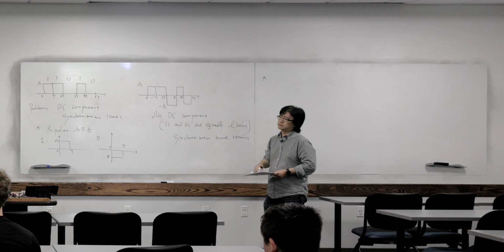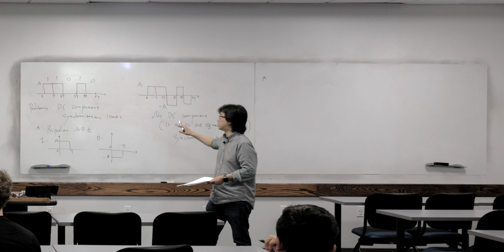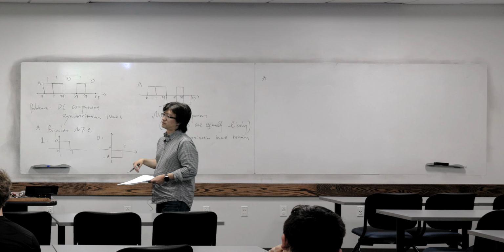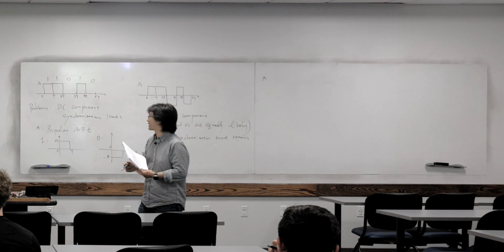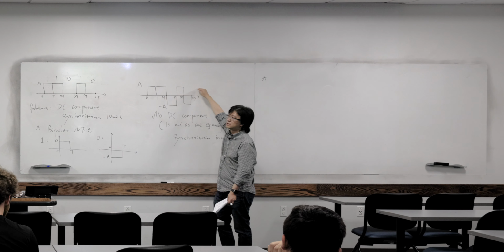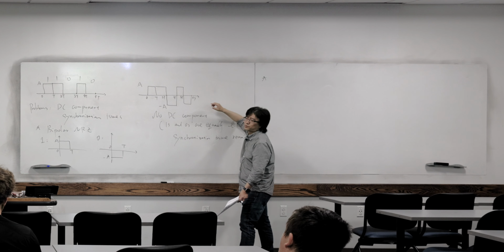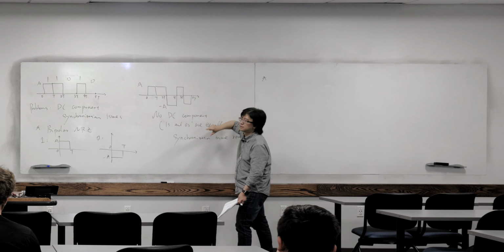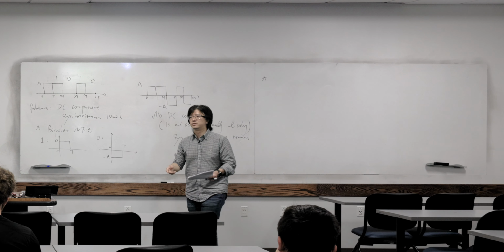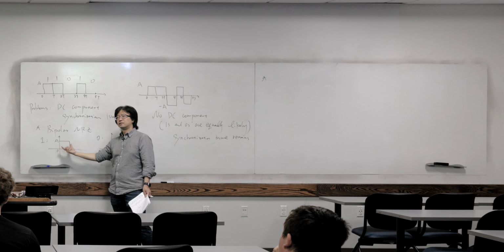How can we design it under the realm of NRZ? We don't want, let's say, if we transmit all ones, it's all flat here. If we transmit 0, it's all flat here. That's not what we want. We want the signal to be changing. How can we make sure the signal is changing? So can you tell me, can you design a pulse shape?